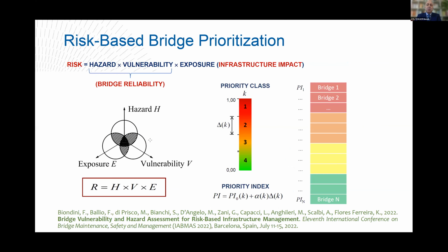In the proposed approach, the risk level and choice of bridges to be subjected to prioritization derive from a documentary analysis of the main risk factors affecting individual structures, including bridge intrinsic vulnerability, condition state, traffic loading, and other site-dependent hazards. Also, the road infrastructure, in terms of impact of bridge closure on the network, functionality and efficiency, is taken into account, particularly with reference to the consequences for infrastructure users.